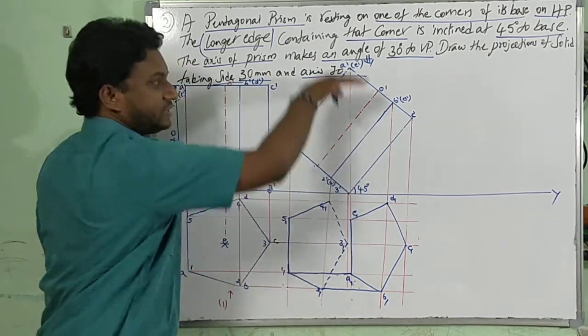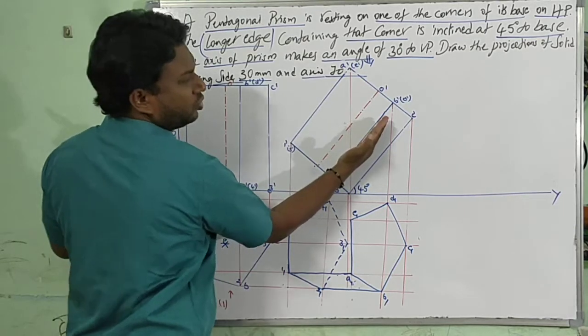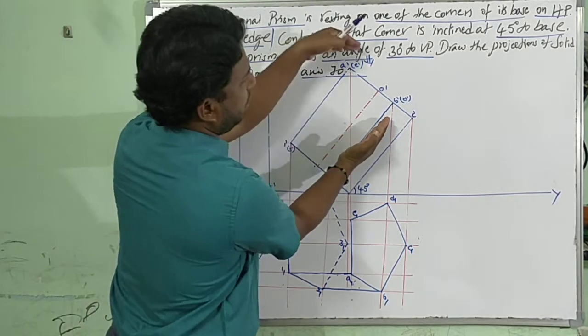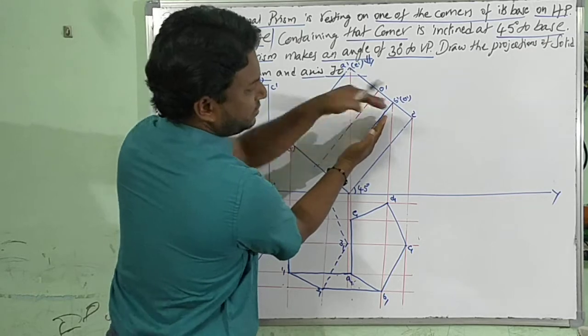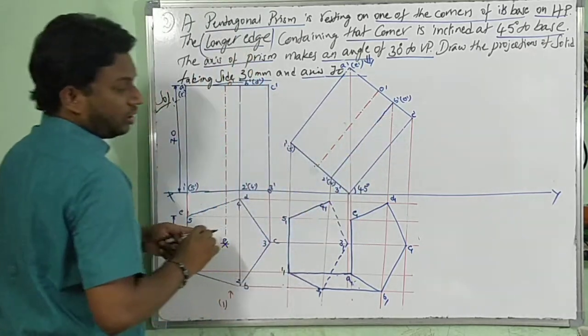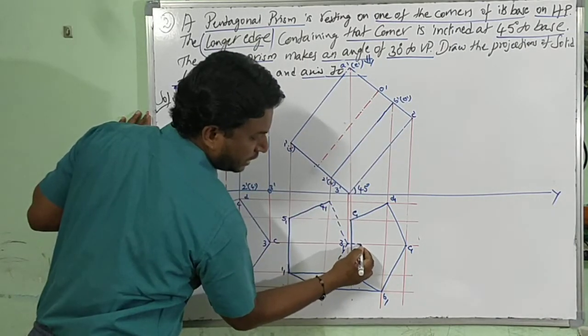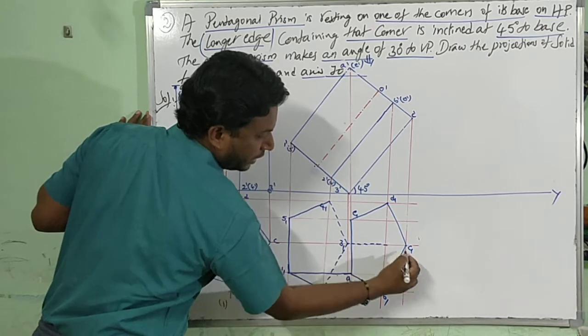Next, C dash 3 dash. With respect to this line, just simply assume this as a plane. When you are looking from this plane, everything at the bottom will not be visible clearly, right? You have to draw hidden. So in that aspect, C dash 3 dash is a hidden line.